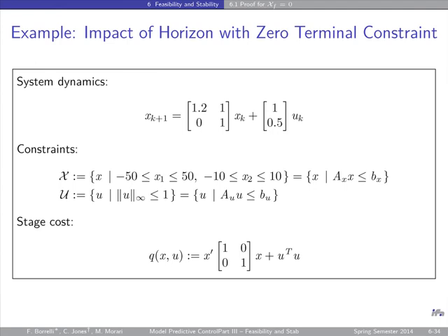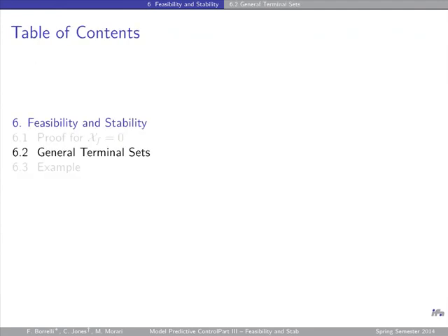You have upper bound and lower bound for both states, so you have 4 state constraints at each time step. So you are going to have 4 times 20, 80 state constraints and 20 input constraints. You are going to have 100 constraints and 80 variables. So this is going to be a problem which is difficult to solve in terms of milliseconds.